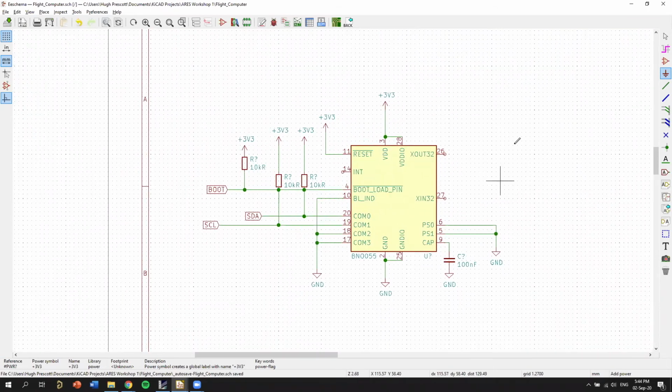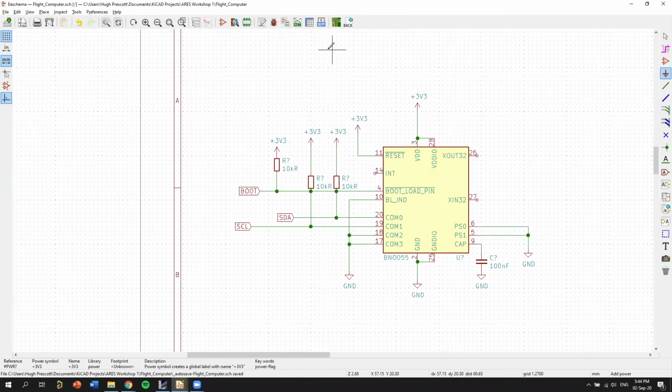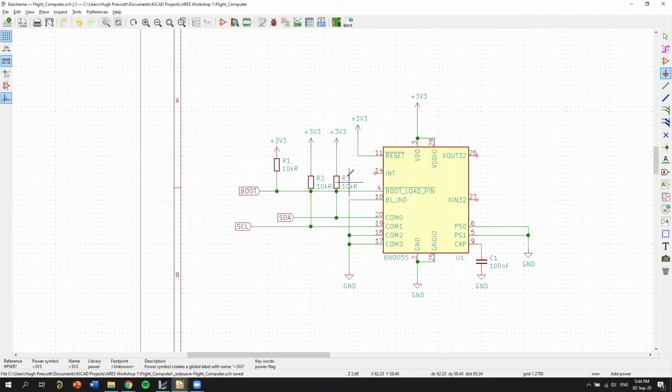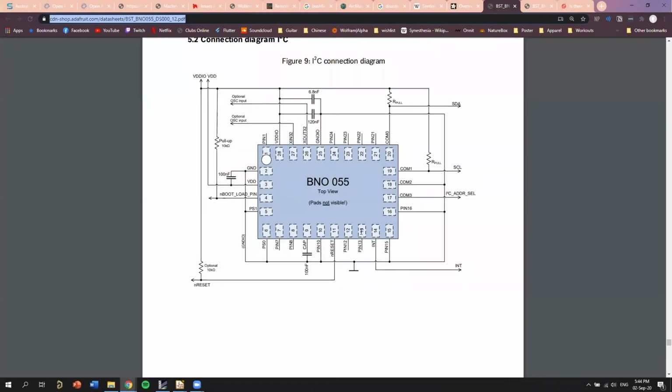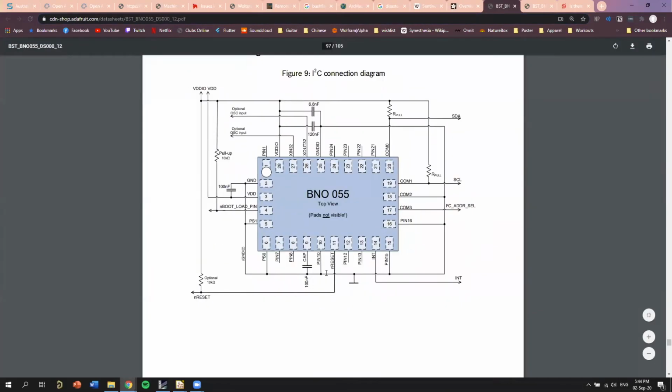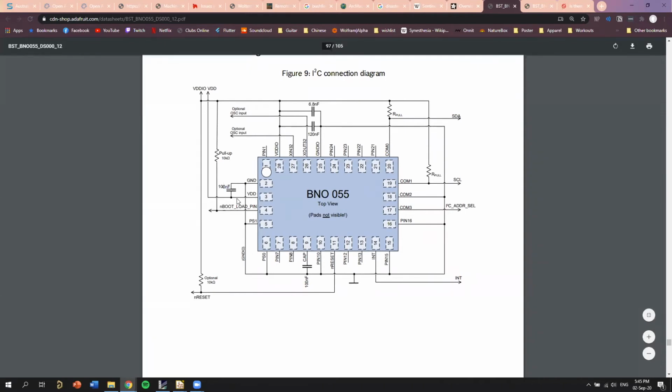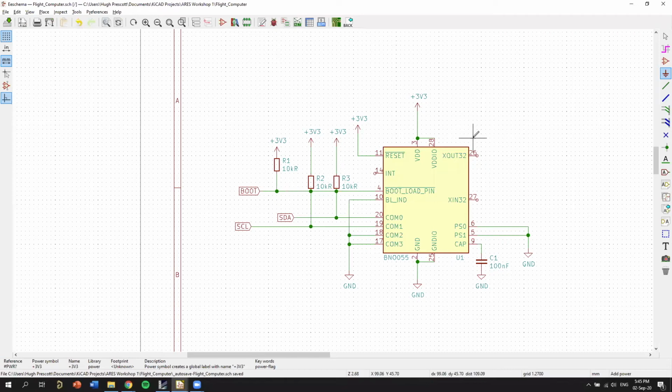The next thing to talk about would be powering it. But before I do that, let's get it onto the PCB and see how it looks with all the parts. So remember, the first thing we have to do is annotate. All of our resistors are numbered, capacitors are numbered. Oh, one more thing I forgot. There's probably some other capacitors we have to add on the input pin. I2C connection. Yep. So here there's 100 nanofarad between VDD and ground. So let's just copy this across here.